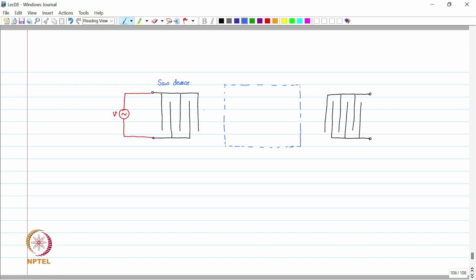Now this surface acoustic wave will be generated using this first IDT. This electrical signal, which is here shown by this red element, this electrical signal is applied on this SAW device and an acoustic wave will generate. What acoustic wave is, the atoms of this piezoelectric material, which is the substrate here, those atoms will oscillate.